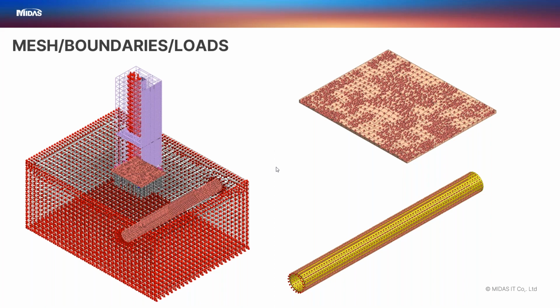cushion layer, because remember the topsoil was kind of weak, as I have mentioned before, but we will see more about the geomechanical properties when I show you the numerical model. So that is why below the 1 meter raft, we have around 1 meter of cushion layer that sits on top of the dense sand, and that does the job of cushioning the load from the residential complex to the piles and finally to the ground. And for the tunnel segmental liners, the segments which were modeled as shield before will be converted into segmental liners.